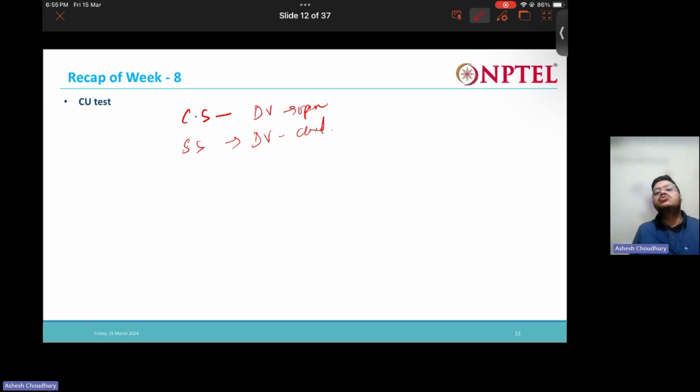Which test you should do depends upon the engineer, the researcher should decide, based on where you are going to use the C and phi values, and under what conditions you are going to use them. On the basis of that you need to make an engineering judgment about what type of test you need to do, whether UU test, CU test, or CD test.